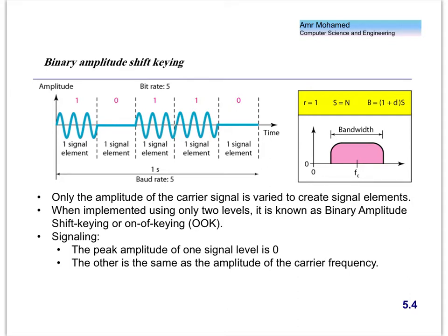So, of course, the good thing about this, in terms of pros, is that this is the simplest form of the broadband communication schemes, the binary amplitude shift keying. Sometimes they call it on-off keying. Why? Because the carrier or the analog signal is just a sine wave, and we just turn it on or off. So when we turn it on, the sine wave replaces the 1 bit. When we turn it off, it represents the 0 bit.